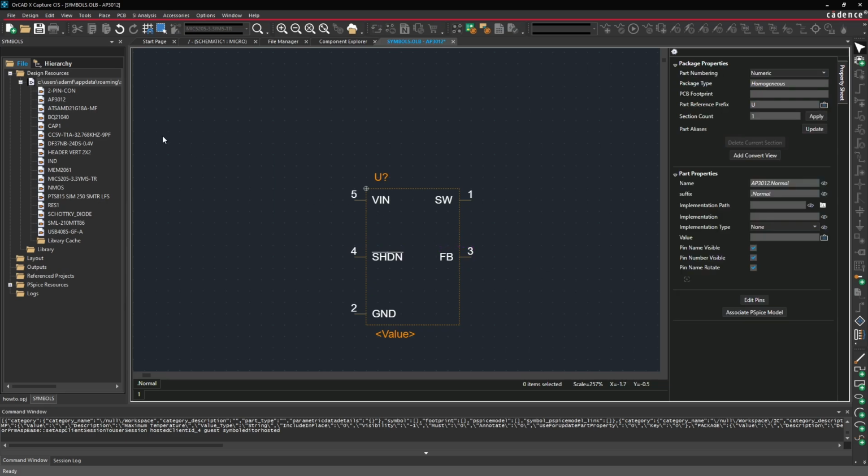So what we've done is if we expect the input voltage into this chip to come in from the left side, it will connect nicely to the V-in pin as well as the ground reference. The switching pin is on the right side here, and we kind of expect for a boost regulator to have an inductor above the component, and that'll connect nicely here, as well as the feedback pin will be connected to a voltage divider made from resistors somewhere over here. So that just makes it easier to organize the components around this part that we're making.